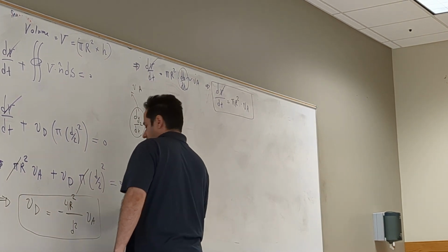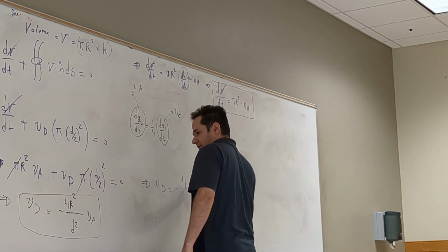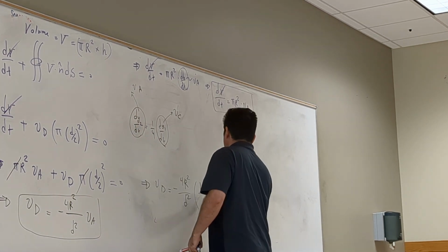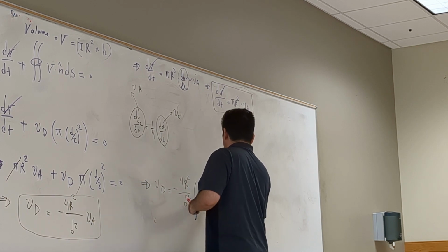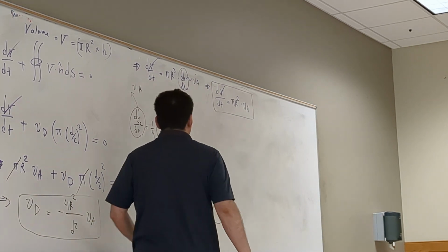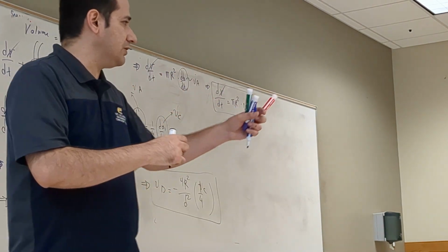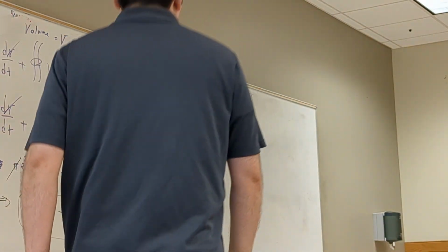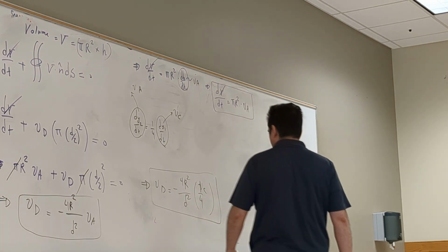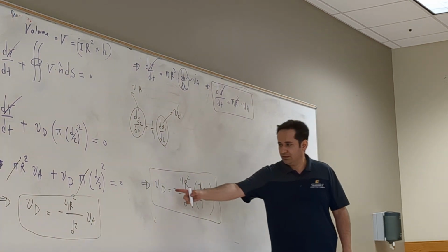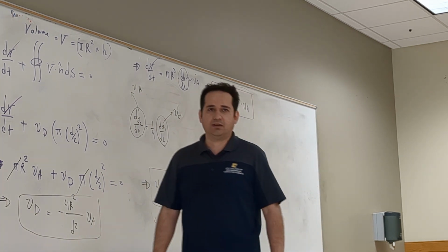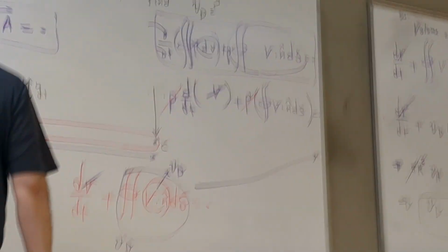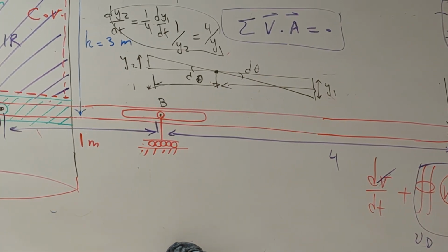So you get the final result, VD is equal to negative pi 4 r squared v squared for VA. We just put 1/4 VC. I just wanted to find the parametric closed form solution. But you could just use the calculator, like you said, 0.2, 0.1, do all the calculation, and that's the final result. Now, when you plug the number in, you see that velocity is negative. What does it mean? Because you see this mechanism, when one side goes down, the other goes up. So the direction is negative.